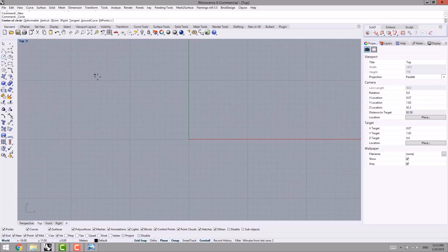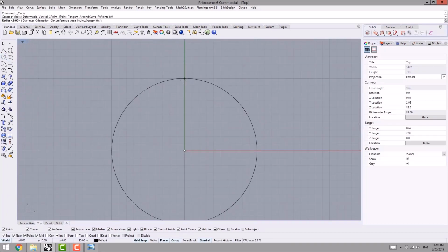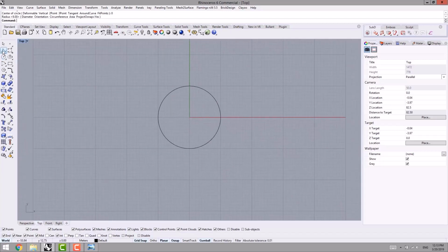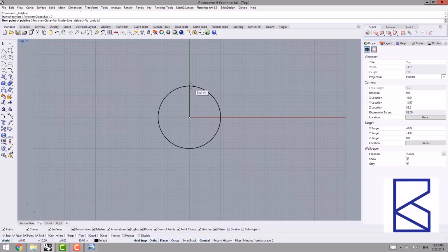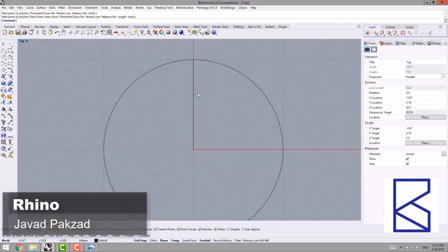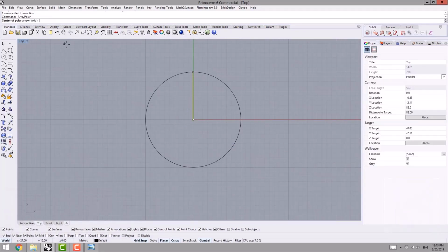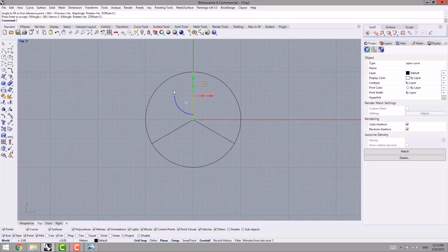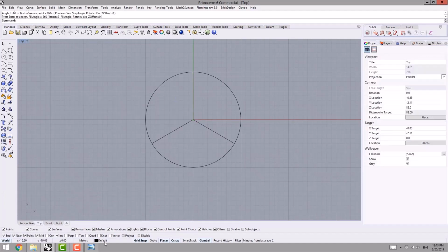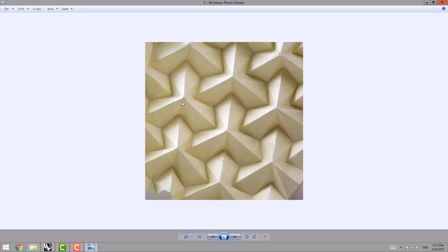And then I open the top view, then I sketch a circle at the origin point 0 and 10 as radius. Following that, I pick the polyline, then I sketch a line from the origin point. I select the line, then I start the command of array polar. I specify the center 0 and then the items 3 in 360 degrees to design the main frame.